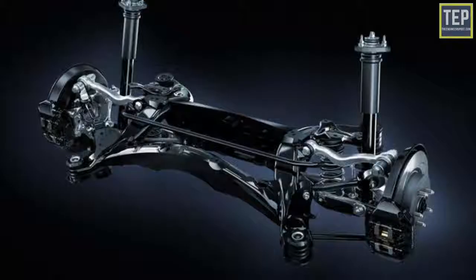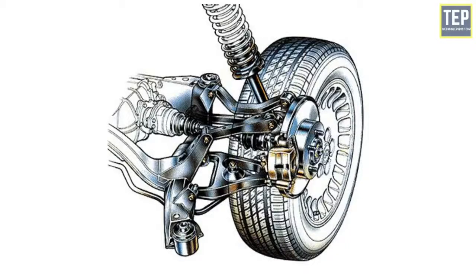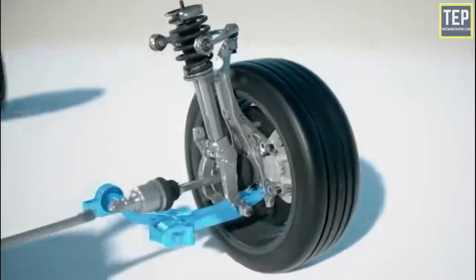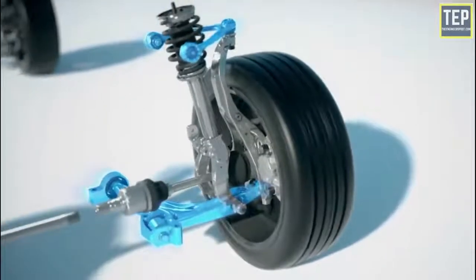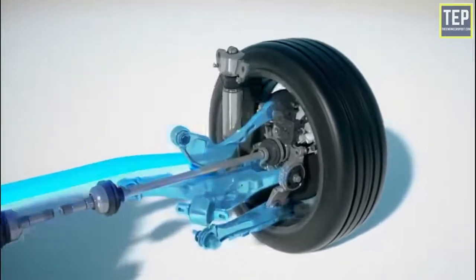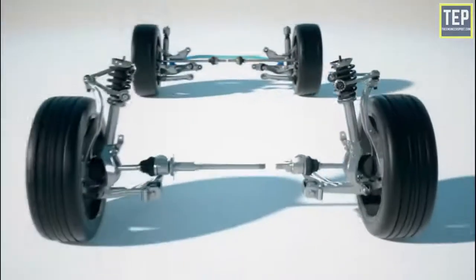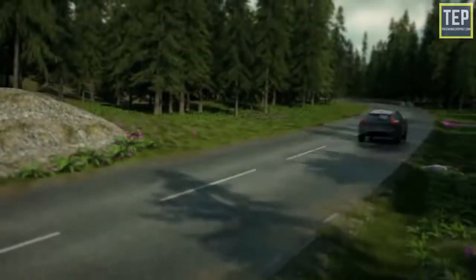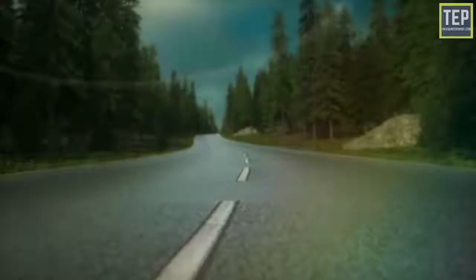Multilink is a suspension developed from Double Wishbone and Multilink that has a fairly complicated construction design because it has separate parts that are held together by joints. This type of suspension has a quality grip, and controlling the car becomes easier. The Multilink suspension also has many variations. If this suspension is damaged, then the replacement process takes a long time, and the spare parts are still rare, so the price is relatively more expensive than other suspensions.